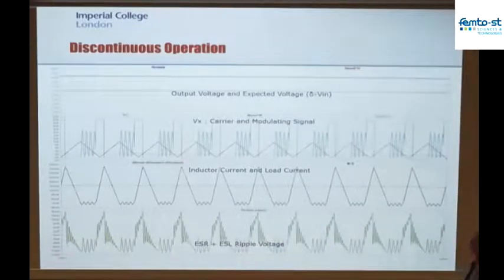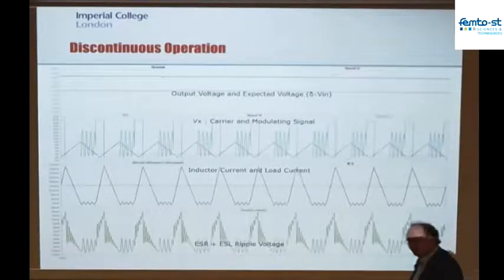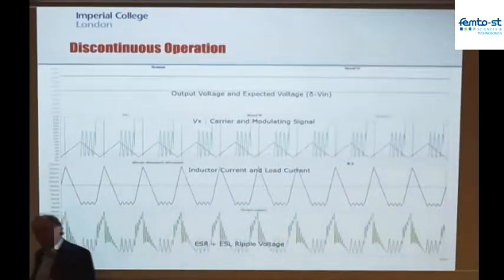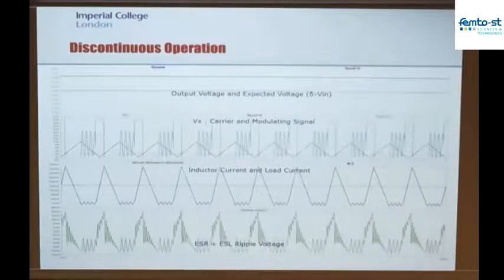And these oscillations actually come from a ringing between the main inductor in the circuit and the parasitic capacitance on the PN junction of the diode. And that is potentially also leading to a little bit of extra power loss. It's also potentially bad from the perspective of electromagnetic interference.